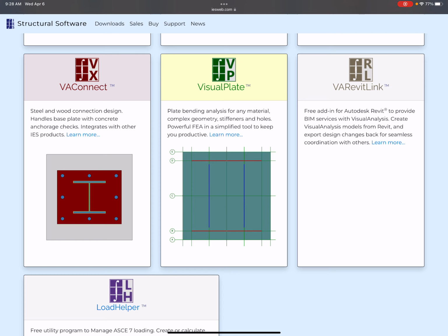Did you do that? No. In general, what ends up happening is the tables in AISC 360 for a typical shear tab. I don't have the numbers in my head now, but when you're doing it a lot, some numbers stick in your head for what a 3-bolt connection can do, 4-bolt, 5-bolt, 6-bolt, and then you look at those members, whether it's W12s and then 14 and 16 and then 18. You look at the max reaction. If that one is okay, then all the other ones are okay.